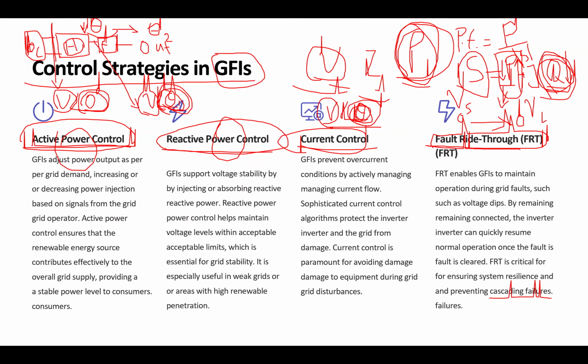Like even in the HVACs at your home, and even in the refrigerator, they have it now. There is a capacitor as a starter for each of those induction motors. That capacitor provides the rush of reactive power that the motor needs, so it would compensate that reactive power, so the voltage would not see the effect, the grid would not see the effect.